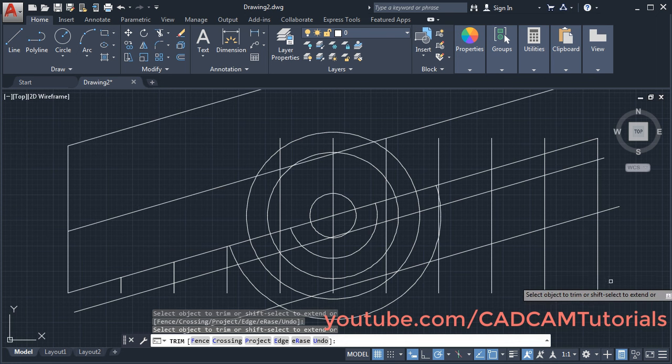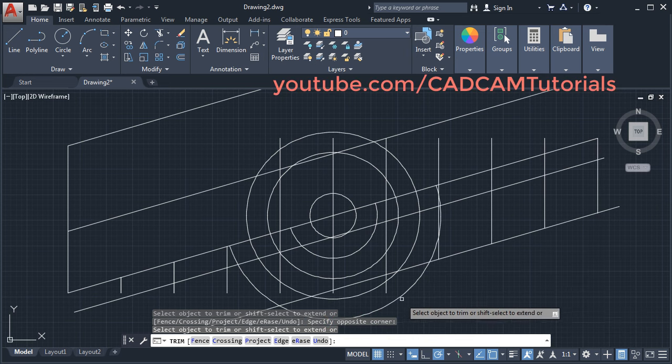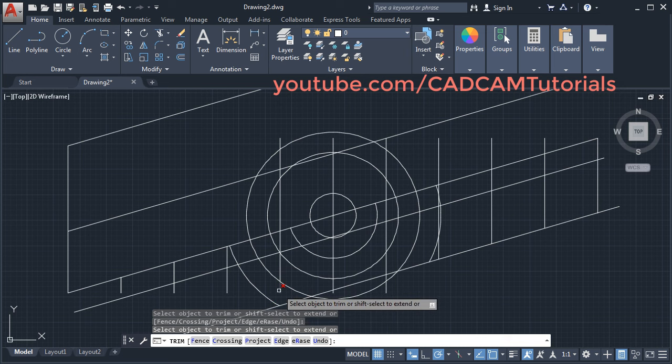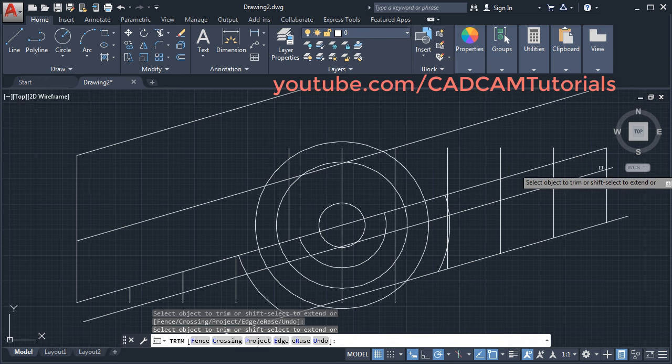You can also use crossing window. Just click on the object you want to remove, so it will be removed. Suppose I want to remove this. And once crossing stops, then it will not be trimmed. Then if you want to remove this object, then you will have to use the erase command. So in this way you can use the select all option, and press enter to stop the trim command.